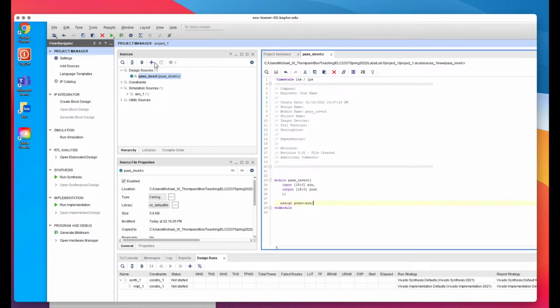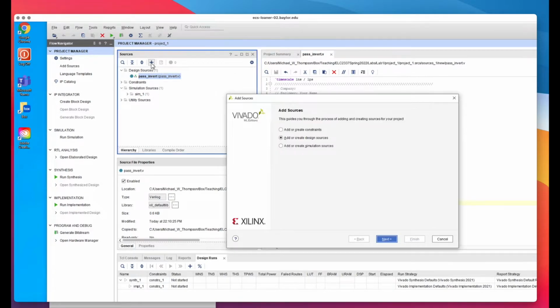All right, the next thing I'm going to do is create the wrapper module that lets me communicate what all the connections need to be between the external pins and switches and things on the board to the internal gate configurations and logic configurations that are generated by Verilog.